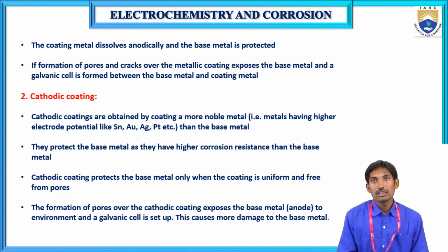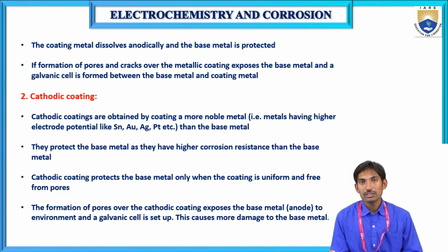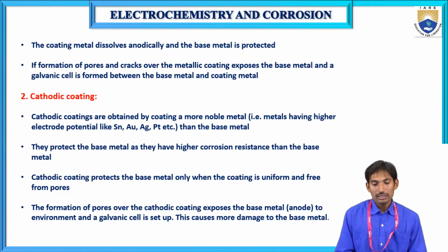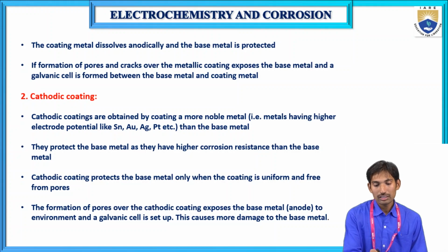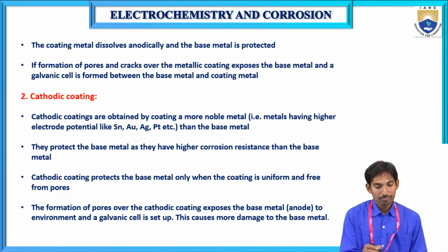The coating metal dissolves anodically and the base metal is protected. Already I have discussed in previous videos that the anode part undergoes oxidation. Meaning the anodic metal coating undergoes oxidation, so it dissolves anodically. It sacrifices its life and protects our base metal.